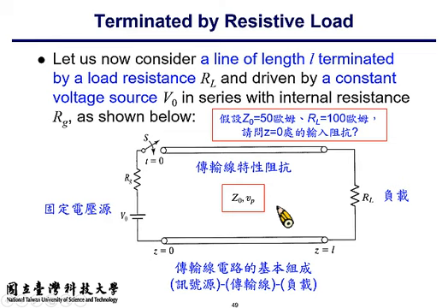Because the two sides are terminated with resistors, which means they absorb energy, the difference will become smaller and smaller. So the magnitude of higher order terms will go down eventually. So eventually, you will reach a so-called convergence or saturation on the transmission line.